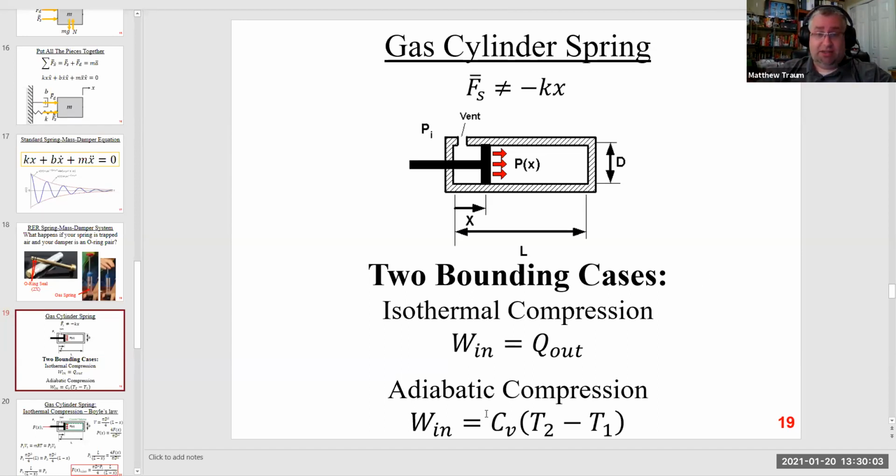If you've succeeded in making that boundary adiabatic, then what does the first law look like? All of the energy that I put into the system as this boundary work, the PDV process, is manifest as an increase in internal energy of the gas. For an ideal gas, the internal energy is a function of temperature only, and so the gas is going to heat up.